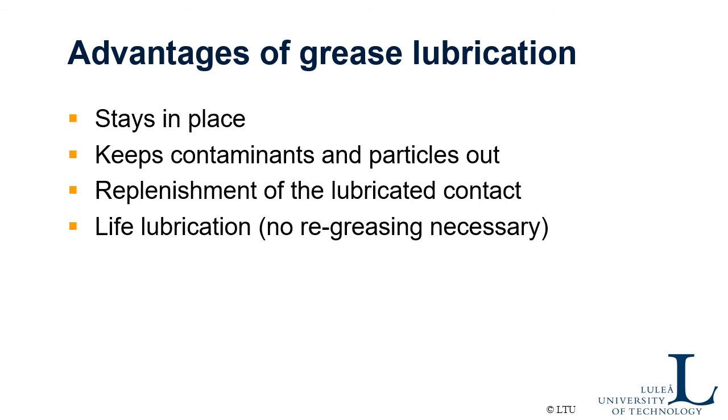So the EHL equations that I have been showing in other videos are not really true for this starved problem. We normally call this type of lubrication starved lubrication because it's not fully flooded lubrication. And normally when you apply this grease, you apply it for the whole service life of the bearing. Even if in some bearing applications, you put new grease there continuously.